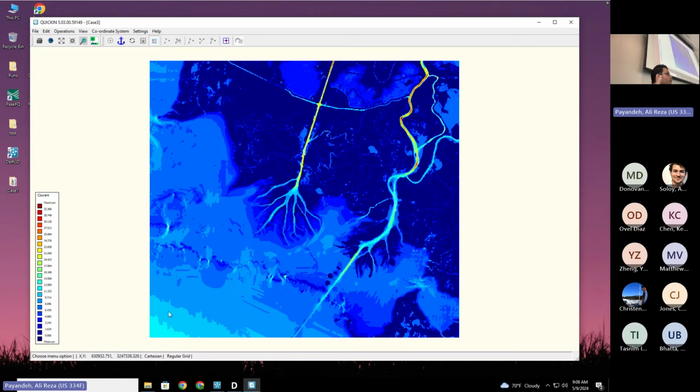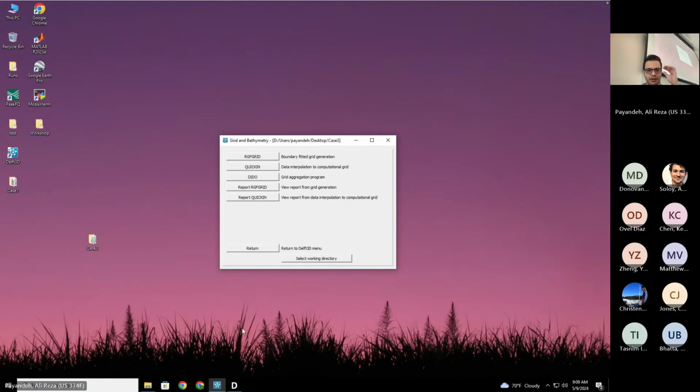Obviously, it depends on your model settings too. In river settings, in which we have a unidirectional flow, you can have higher Courant numbers. It's not a big deal. But on an open boundary, it's better not to have it. For our case, we are sacrificing the Courant number criterion a little, and it works for us. So this is how you can check Courant numbers.